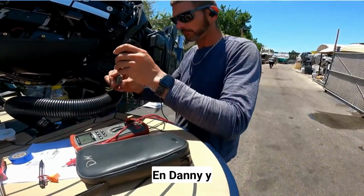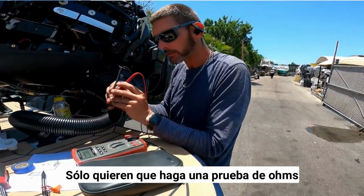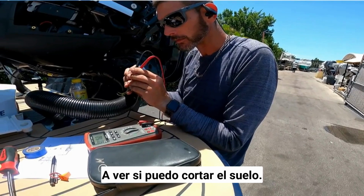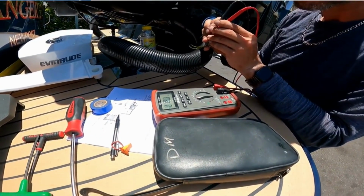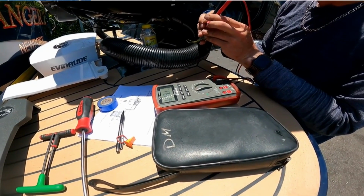After Danny spoke with the people of Evinrude, what did they recommend? They just wanted me to do an ohms test to see if I got a short to ground. Check resistance on the harness, on the solenoids.